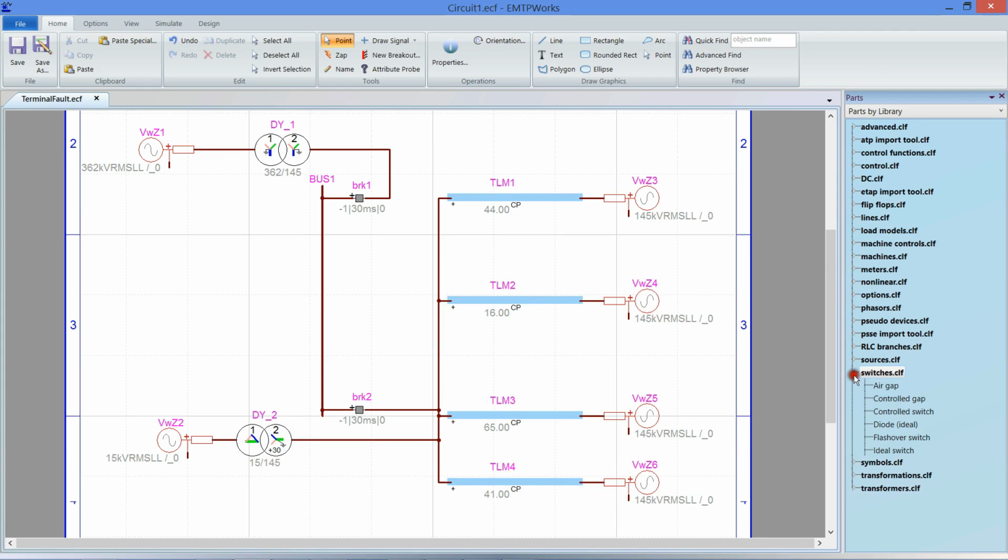So then let's model the faults. In EMTP we model the fault with switches. For example, you close a switch to the ground to make a fault directly to the ground. You can close only 1 pole, 2 poles, 3 poles, and you can connect 1 pole to another to do a line-to-line fault, so you are completely free. You can also add a resistance to simulate a fault with resistance. So you can model all types of faults, balanced and unbalanced.